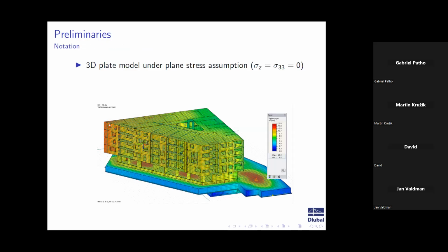So what we will consider, our assumptions are that we are dealing with 2D models. From masonry, you almost always build walls, so you do not need any 3D mathematical model. If you need to go that deep, you really need to apply different models for mortar, for masonry, and the binding of these materials. In larger structures, you always want to model 2D. In our software, however, it's not a purely plate model. We have a shell element.